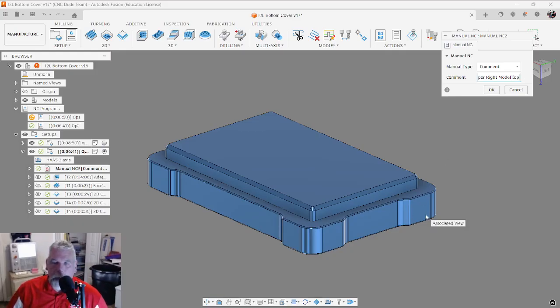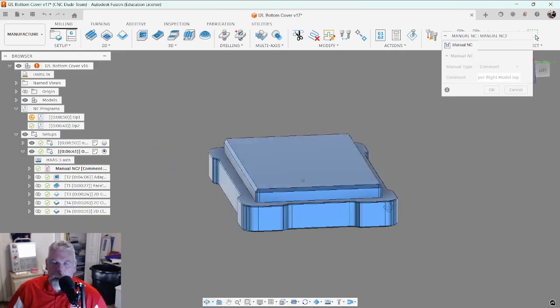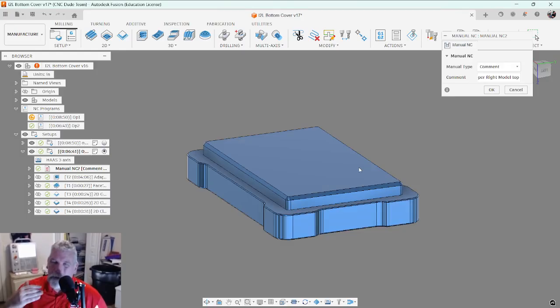So because I already have some nice flat surfaces, I could probe this in the machine and the top of the stock, but the top of the stock's not really good enough. You could probably sort of calculate it from there, but I like using the old trusty 1, 2, 3 block. I can probe the same surfaces, probe the top, and I know the 1, 2, 3 block's exactly 1 inch above the bottom, so I prefer to use the top as my Z0.